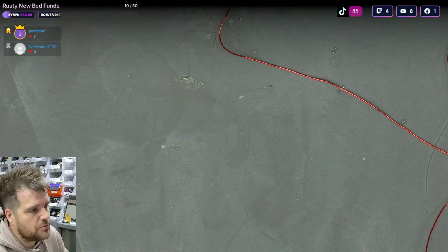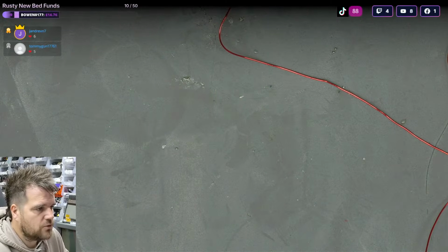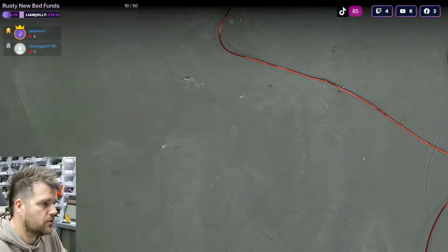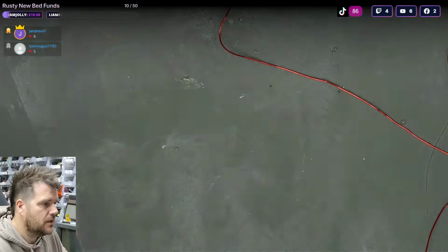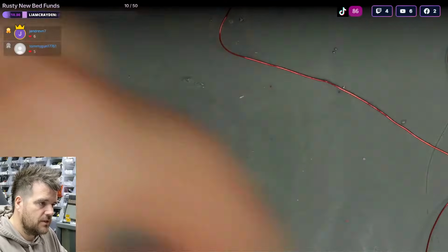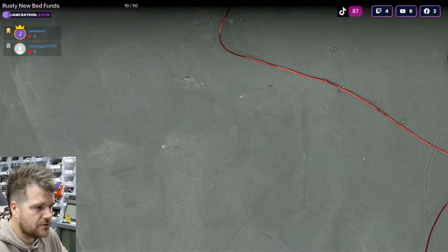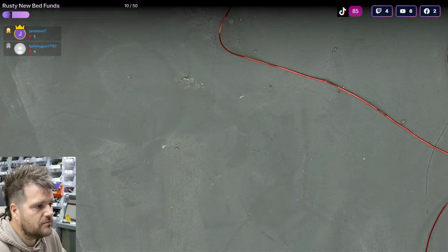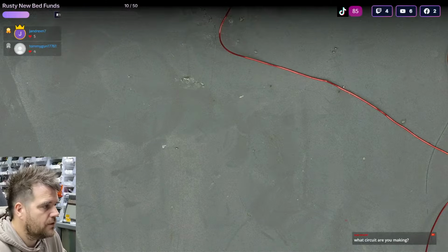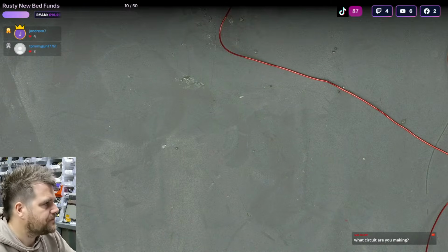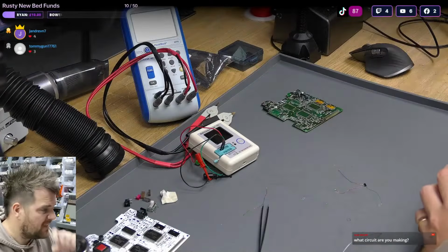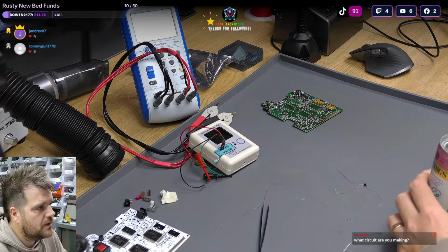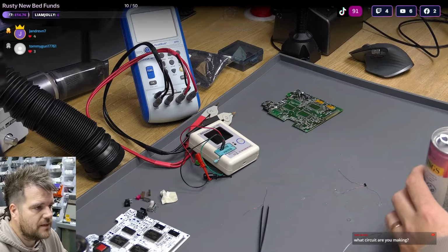Clean your cartridge port with vinegar, like warm white vinegar. Put vinegar in the microwave in a little bowl for a minute so it's pretty hot, and then you can either tip it in the cartridge slot slowly so it touches, but ideally you want enough vinegar that you can dip the cartridge connector in it and leave it for no more than a minute. Once you've done that, inspect the cartridge port. You could always try and bend the pins up with a tweezer, and then try again. Clean your game with IPA and see if you get game load.